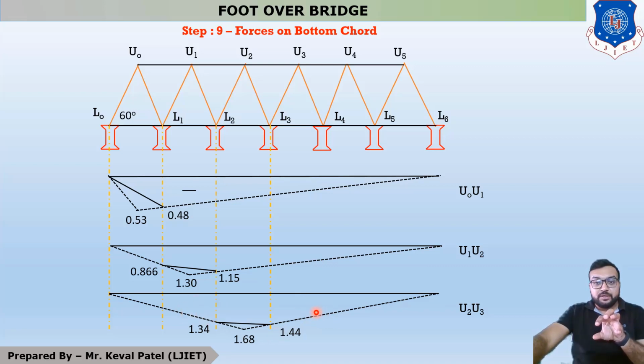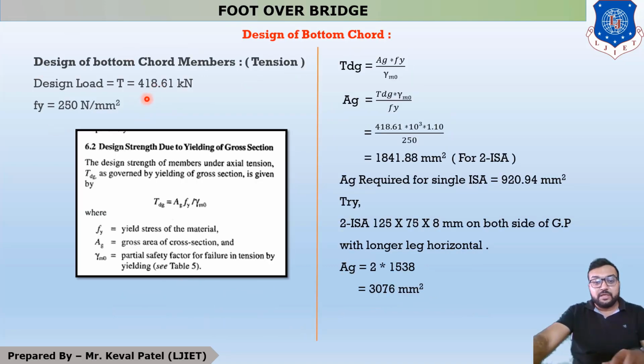Second area is this point. For this point you have to refer to this triangle, and this triangle is 1 half base altitude. Now the remaining portion is this portion, and you can see that this is your trapezoidal portion, and for the trapezoidal portion your area is (a plus b) into h by 2. So with the summation of two triangles and one trapezoid you will get your total area, and this total area is multiplied with total UDL and you will get your maximum answer, 418.6.